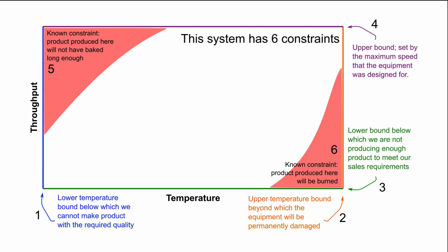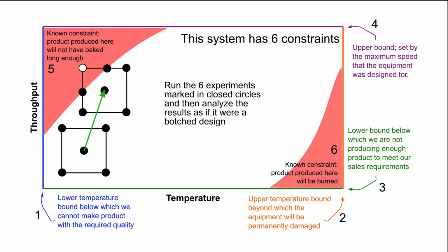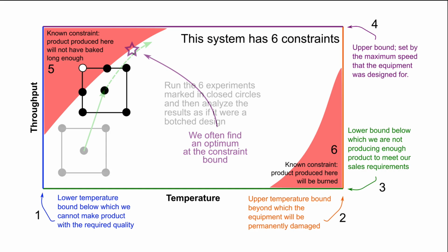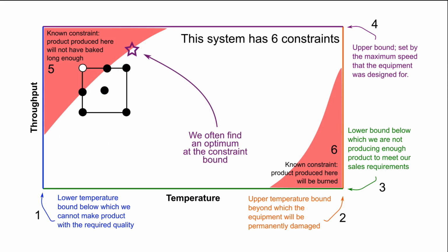For example, a constraint that runs along this direction, shown in red, and anything beyond it we cannot go and run over there. What if the path of steepest ascent was showing a promising direction along here in green? Well, then we modify our path to obey that constraint. But we have to always obey safety requirements in our process. They're of primary importance, and we have to find our optimum within those restrictions. And I'll end by saying it is not uncommon to find your optimum right at the boundary of a constraint. We see that in engineering systems frequently, and it's likely to occur in other systems as well.